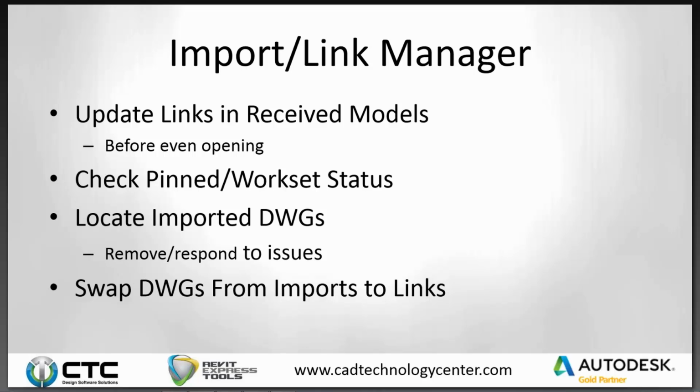Also, after you're in the model and you're taking a look around it, if you use the Import Link Manager, you can check the pin status and the workset configuration of all of the links and imports right in that interface, and modify those pinned and workset statuses on the fly, instead of having to track down the actual object, clicking on it, checking it out, changing the workset or changing the pin status. You can do that right in the Import Link Manager window. So it's two of those things that are really critical, querying across the board if they're all pinned or not. This is a really easy way of checking that.